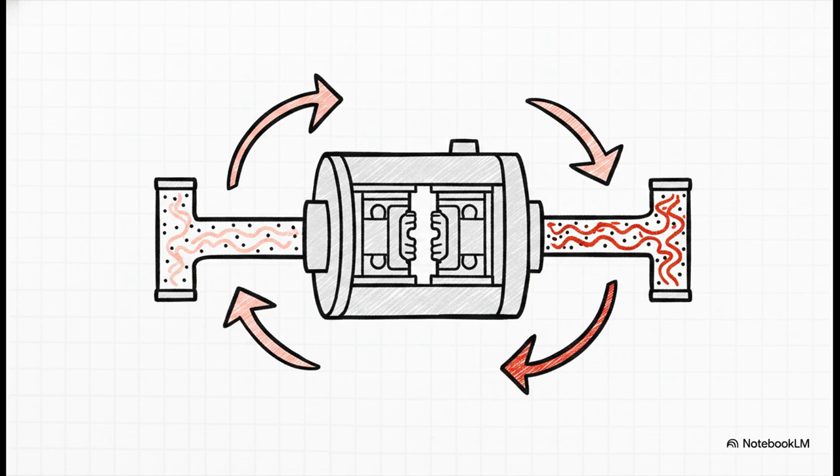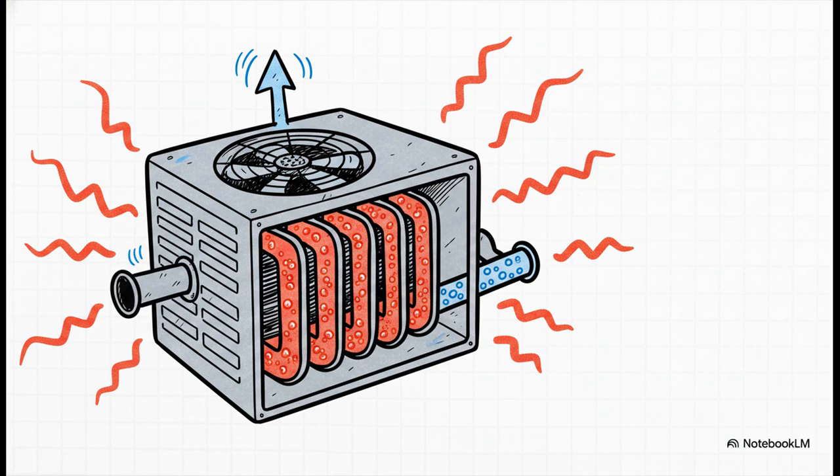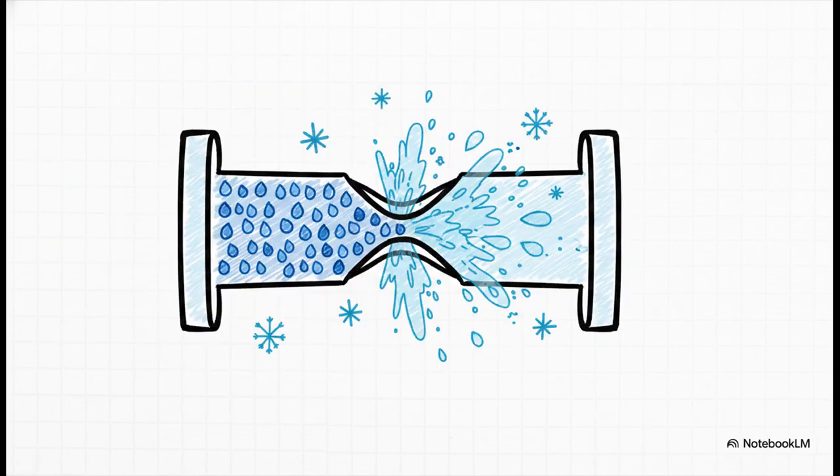Okay, so now, superheated and highly pressurized, that gas flows into the outdoor condenser coils. Out here, a really large fan pulls the ambient outside air and blows it right across those coils. Because the pressurized gas inside is hotter than the summer air outside, the heat transfers right out of the refrigerant and into the outdoor air. As it rejects all that heat, the refrigerant cools down and condenses, turning back from a gas into a liquid. Boom! The heat from your living room has officially been banished to the backyard. But hold on, we aren't done yet.